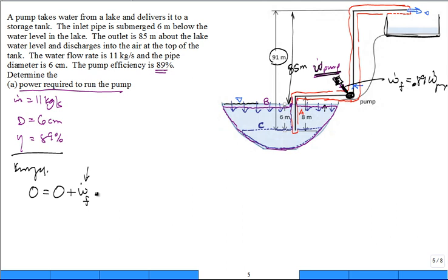All right. We have the mass flow rate in and mass flow rate out. This is all in at state 1, all out at state 2. So for the mass flow rate, I have its enthalpy in, enthalpy out, kinetic energy in, kinetic energy out, potential energy in, potential energy out. All that makes sense? I'm going to have to limit you on questions.